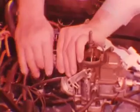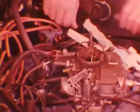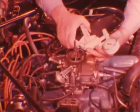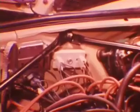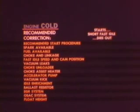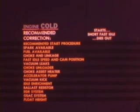On idle enrichment carburetors, the system must go into action. If engine speed changes when you apply vacuum to the diaphragm hose, the system is working. In the ignition system, an open ballast resistor will also cause an engine die-out as the key is released from cranking position. Where you have an engine that starts, runs at fast idle for a short time, and then dies